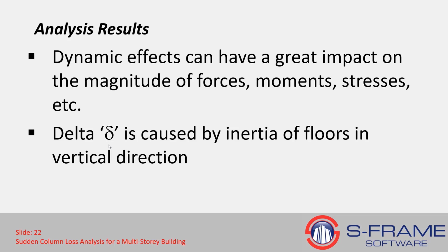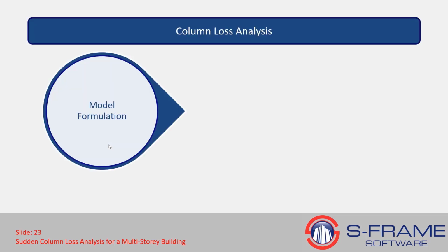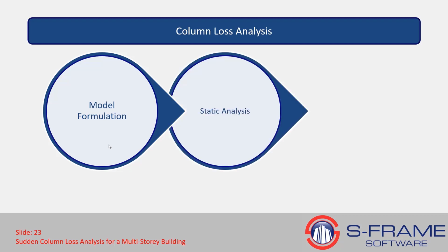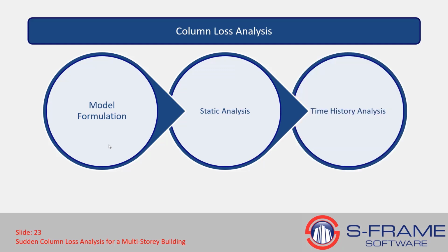So in this presentation, we started off by getting a better understanding of our structure and running a vibration analysis to understand the dynamic properties. We chose to use a time history load to represent the influence of our original column before the removal, and ran an initial static analysis to see the influence of the column in terms of actual load prior to its removal. Once we have all that information, we can then run the time history analysis to see the influence of that removal of the column and see how the structure behaves once that is done.